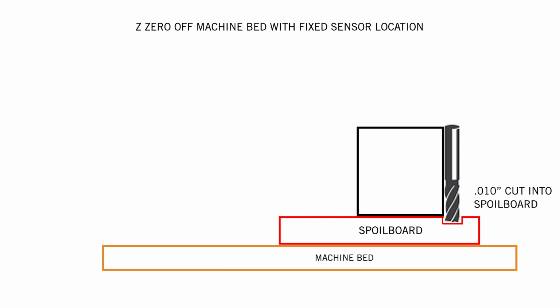So if all you're doing is profile cutting, like for instance, say a puzzle, where you're cutting all the pieces out directly, and you measure your material and maybe the material surface varies a little bit, but you just add some extra so that you're actually machining into the spoil board to get a clean cut on both sides, then Z-zeroing off the top is no problem at all.